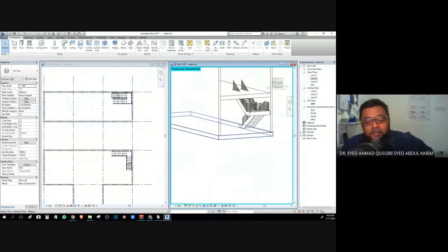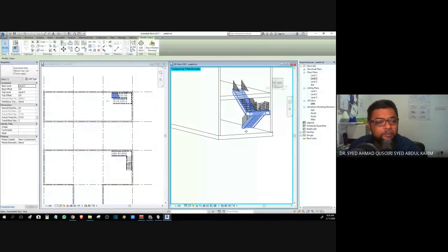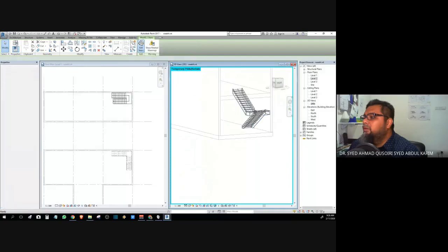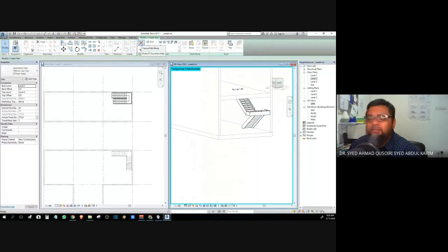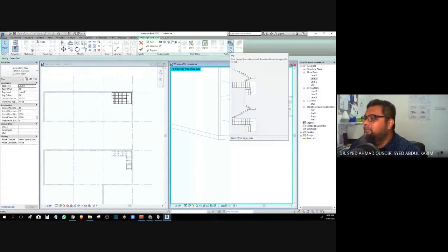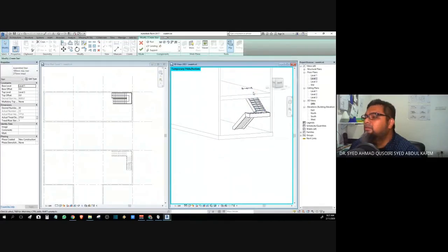There's an easier way. You just highlight the stairs. You just click on this step part and it highlights everything. So go to edit stairs. And then you can see here the command, it's Flip. Okay, so we press flip. You see, it flips. Click, click.